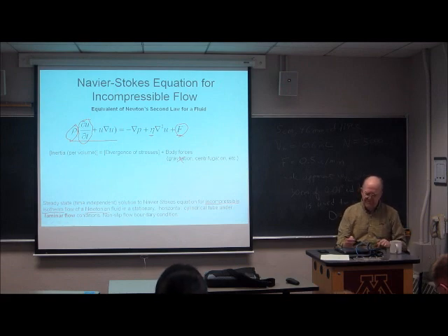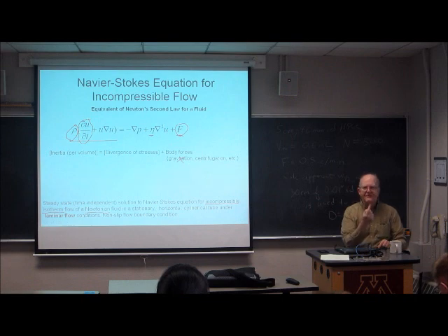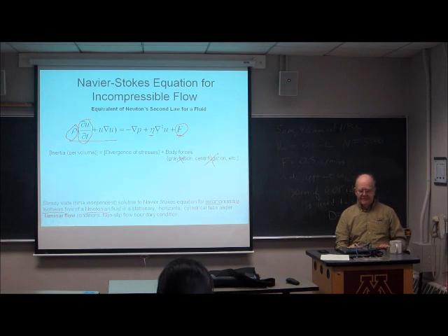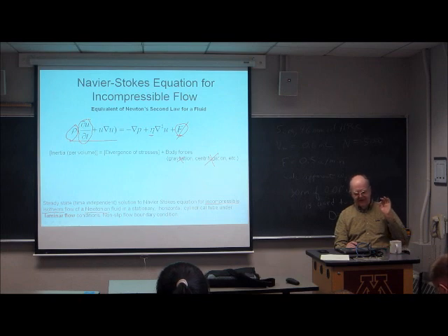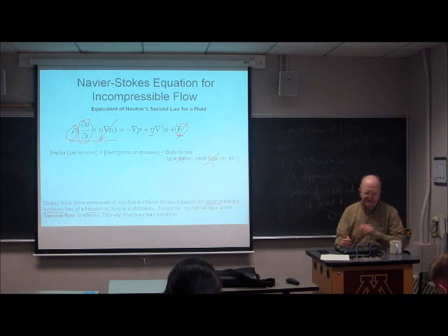And we have to assume that you're not somehow rotating the tube about its axis. And that wipes out centrifugal forces. And that means that term is 0. Now here's the big one. You have to assume laminar flow. And under laminar flow conditions, this times that is negligible compared to that term.